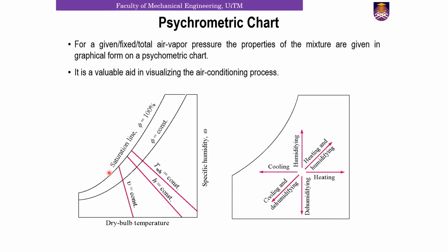The sizing of a typical air conditioning system involves numerous such calculations, which may eventually be very cumbersome for most of the engineers, right? So in order to avoid that, there is a clear motivation to computerize calculations or to do these calculations once and to present the data in the form of easily readable charts. Such charts we call psychrometric charts, right? You can actually represent the air conditioning processes on a psychrometric chart easily.